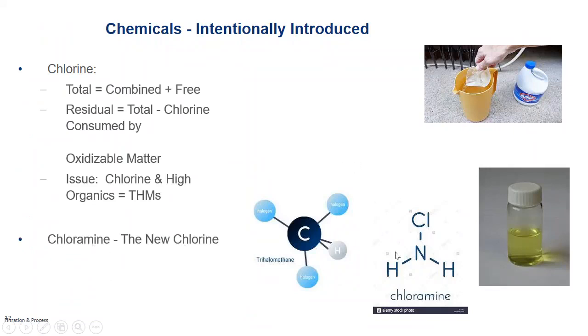Now, chloramine we discussed, growing in prevalence. This is moving into northern climates as well because of its cost efficacy. But there are issues with chloramine. This is a nasal, eye and ear irritant. Your red eyes from the pool are from this stuff. This will also react with copper plumbing if it lingers in the pipe too long, dissolving copper. Some people are really sensitive to amines, skin-wise, and it can cause skin irritations.